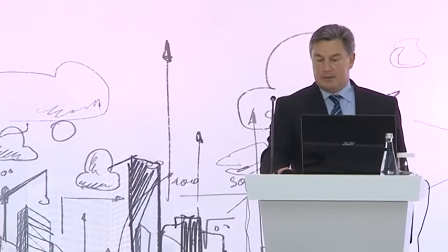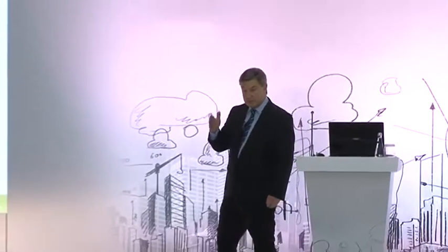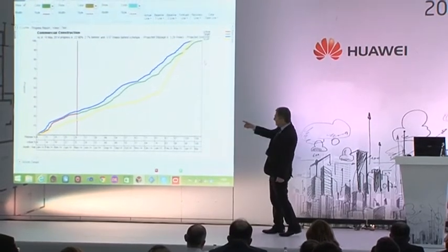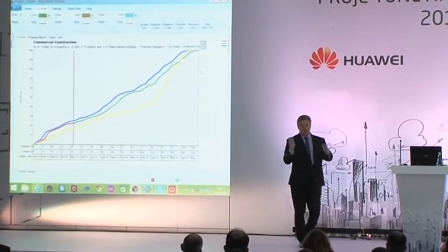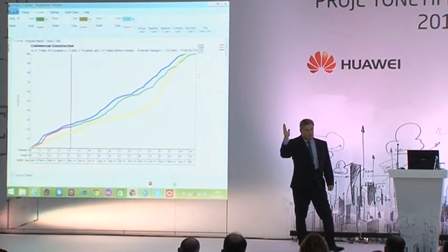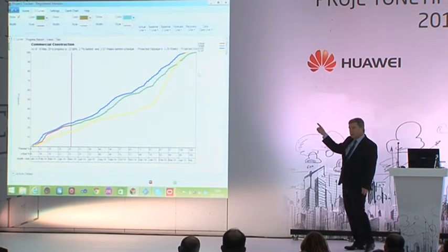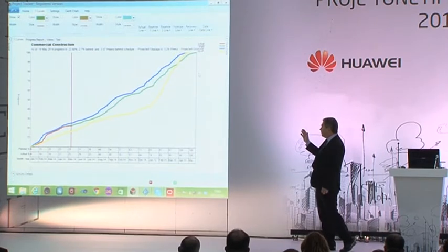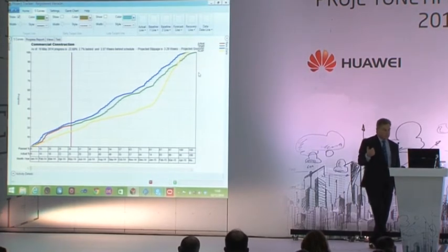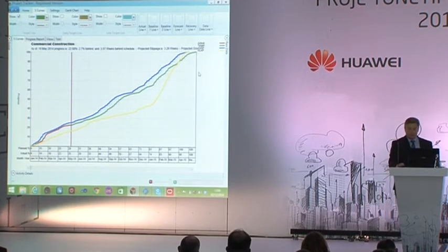So I could stick in my second baseline, which if you remember, I said was my latest possible position, with the tasks in their latest possible position, latest finish, if you like. What that's done, that's created what's called an envelope. And a lot of people like to work with an envelope, so the yellow and the blue. As long as I'm tracking within that envelope, I'm probably doing okay. I don't need to panic too much. If I'm below my latest dates, I'm probably in a lot of trouble. I'm still finishing this project late, but not too bad. It's only 2 or 3 weeks. So we could do something about that. By overlaying these curves, we can see a lot of information.